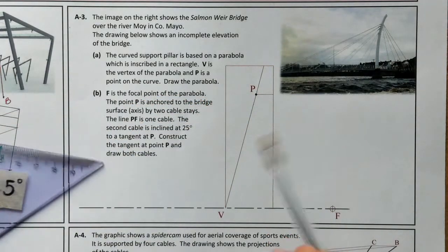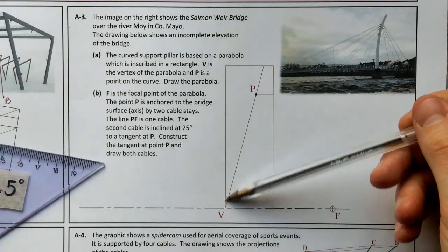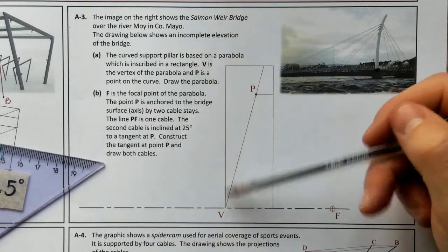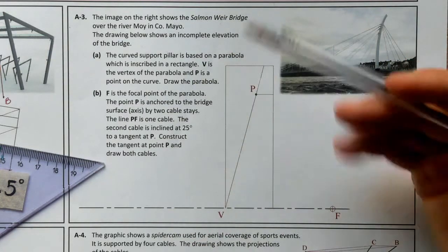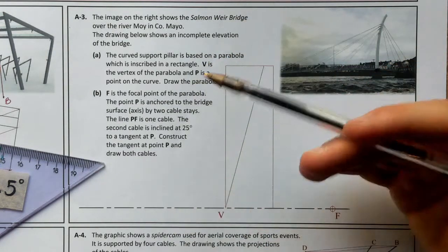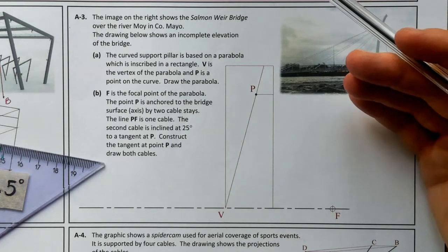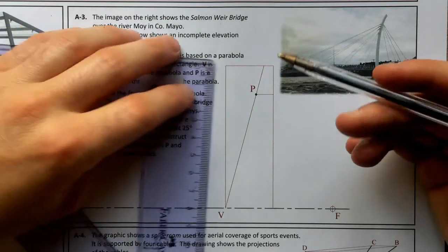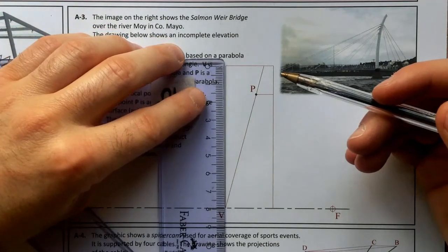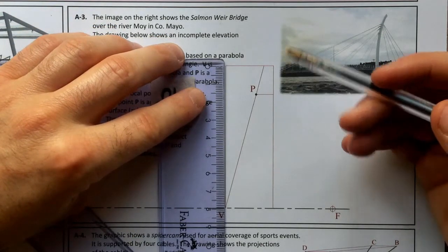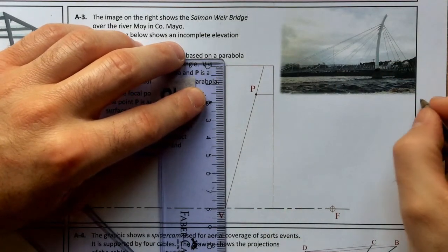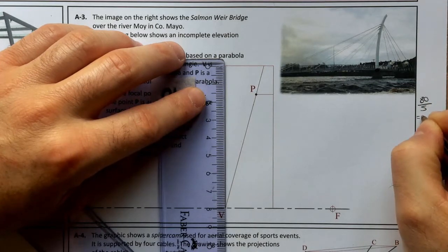So anytime you have a parabola, what you can do is you're going to divide the long side and the short side, or whatever it is, they could be the same, into an equal number of parts. The more parts you divide it up into, the more accurate your parabola will be. So in this case, 80, I'm going to try and make an accurate enough one. I can do 4, 3 would be too little, 4, not bad, I'm going to go with 5. So 80 divided by 5, you can do a little bit of quick maths here on the side. 80 divided by 5 is equal to 16.